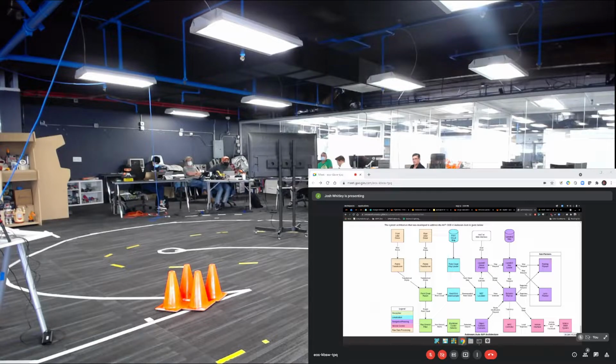So it would make a request to our map provider for Lanelet2, get that back, parse it, figure out how to get through the map, and then pass that global route to our behavior planner. The behavior planner would then take in the pose estimate from NDT as well, but the behavior planner is meant to take each of those segments and figure out how to drive based on a set of waypoints along each one of those segments. So the behavior planner calls a set of sub-planners depending on what type each of those semantic segments is.